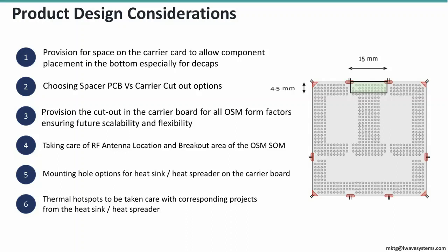But if you go to the carrier cutout option, you save the cost of the spacer PCB and also the assembly cost, but at the same time you have a lot of holes. Some liked it, some did not like it, because if it is a small module, it's fine. But if you go for the large modules, you can have at least 3 cutouts in the carrier board, which looks a little bit odd. And then